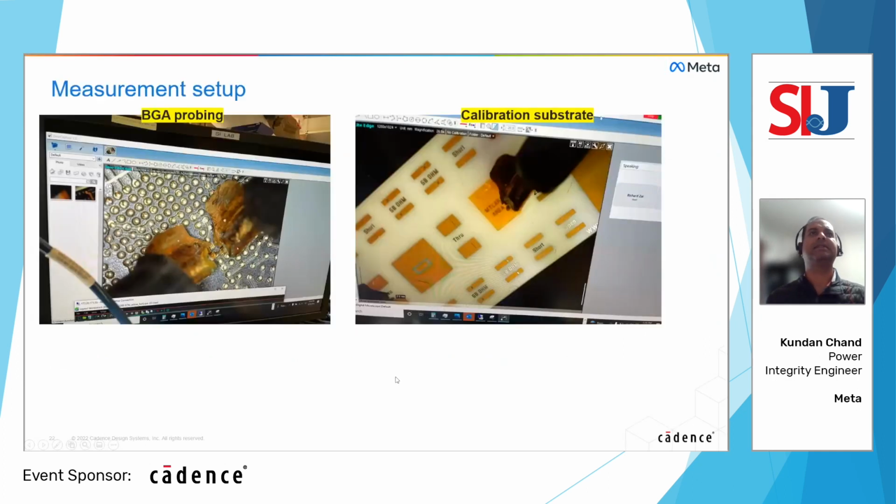Okay, so this is just the measurement setup for that. Again, like I mentioned, we use these Pico probes, and this is showing the calibration substrate from one of our probe partners, and we use this to do the short, open and load calibration.